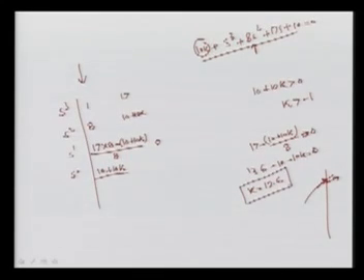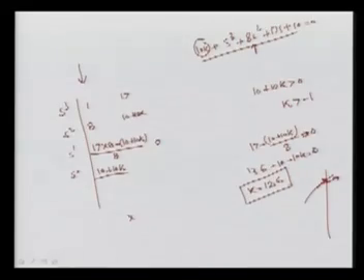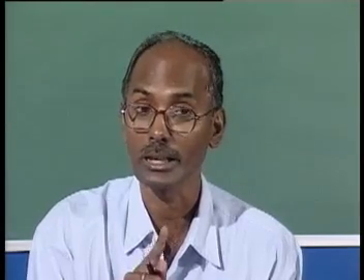Now you can see here the gain value, if for this time constant it is more than that, then your system will be unstable. Means here you can see if this value k is more, this term will be negative. Means there will be some sign change and it will be crossing your imaginary axis. But in the static case we saw for the same time constant, because it was not related with the time constant, the gain at that time.